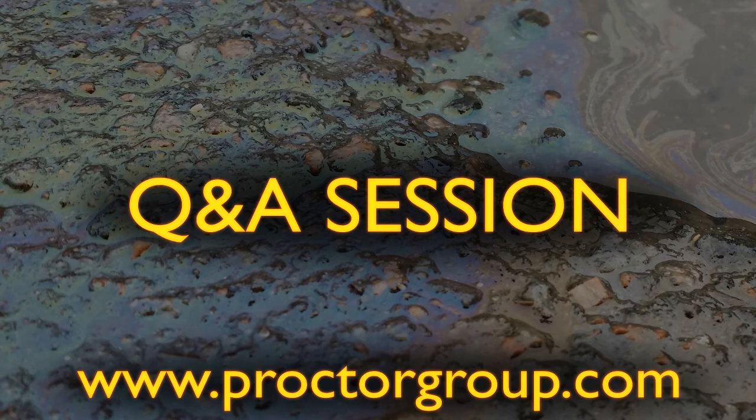Okay, and a question that's coming from Stuart, which is probably relevant to ask just now. Can you talk us through the most common VOC encountered generally within domestic dwellings? That's a good question. There's a whole array of different hydrocarbons that can be on a lot of sites, but ones that we particularly come across are benzene and naphthalene, and we would then recommend our VOC membrane in that situation.